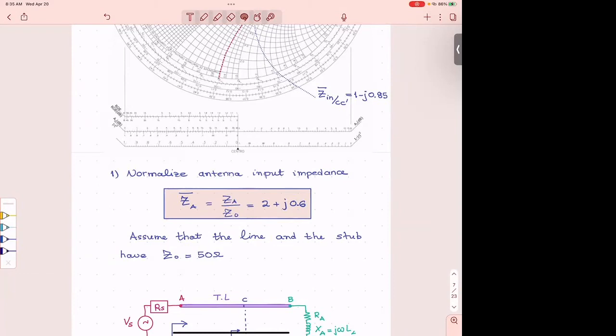On the Smith chart, you have to normalize impedances to Z0, and in this case I'm selecting to use a Z0 equal to 50 ohms. Only in the quarter wavelength transformer is the characteristic impedance specified by the square root. In every other solution that does not involve a quarter wavelength transformer, you are free to select the characteristic impedance of the sections of your lines.